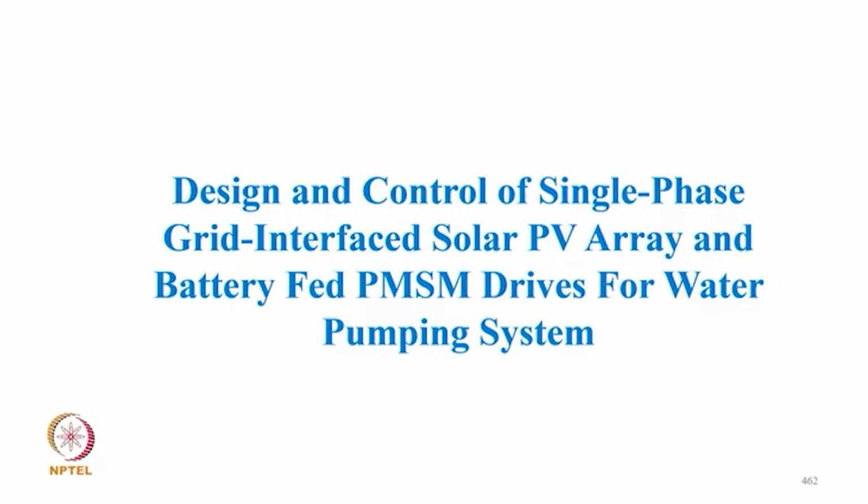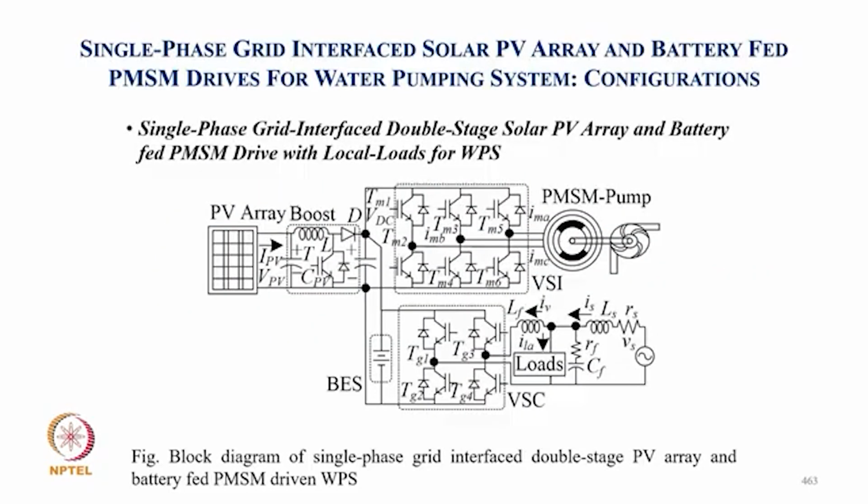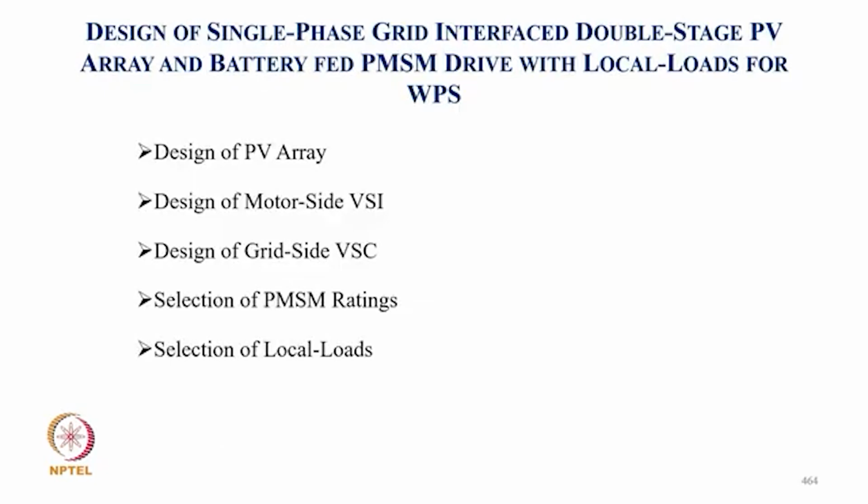And then coming to design control of single phase grid interface solar PV array, battery fed. So here we have a battery which is smoothing the power of PV variation, load variation, as well as the grid availability and non-availability. So you get uninterrupted operation of the water pump.